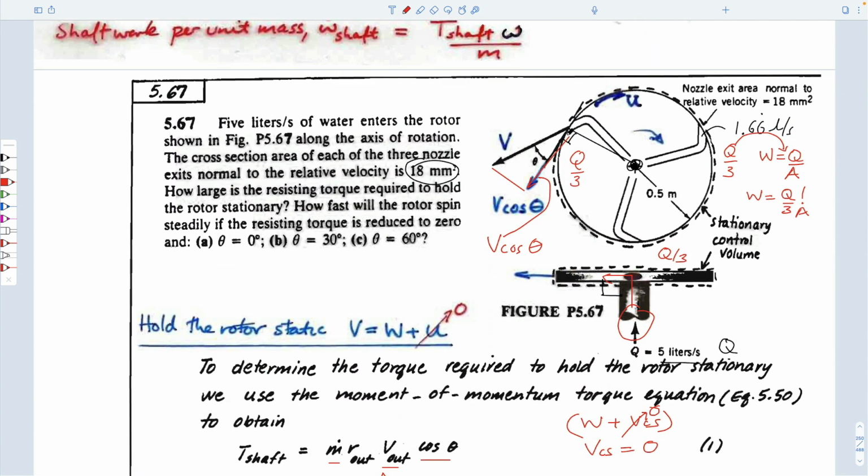If the angle's 0, so if the flow is in this direction here, if it's at 30 degrees, which is at this direction, if it's 60 degrees, this would be V60, V30, and of course V90 would be this. And just your intuition, I hope you wouldn't design a turbine or a sprinkler that would do this, because it wouldn't move. There's no net force acting tangentially, and therefore there'd be no torque. It would just sit there on its own without any force being applied.